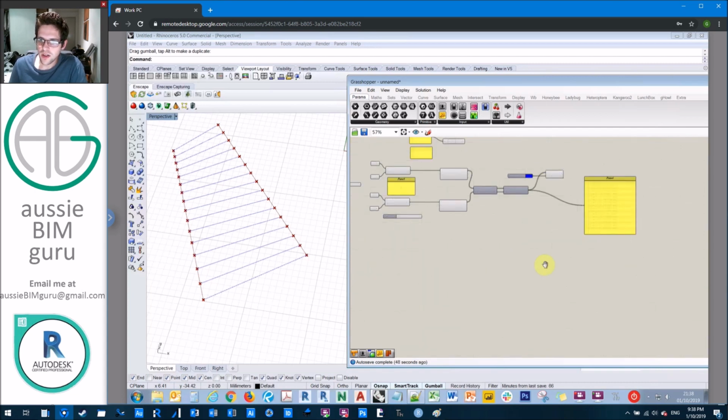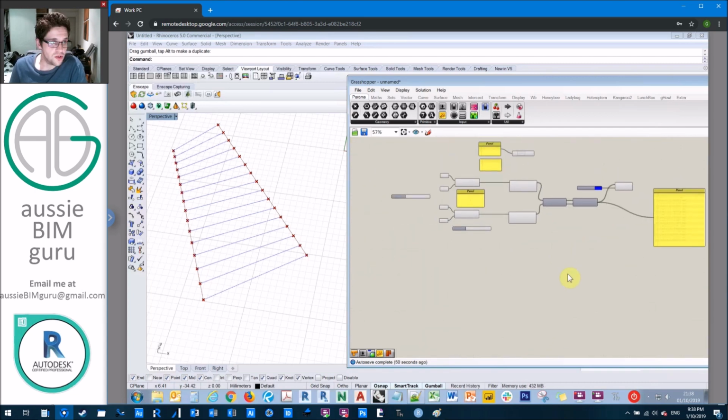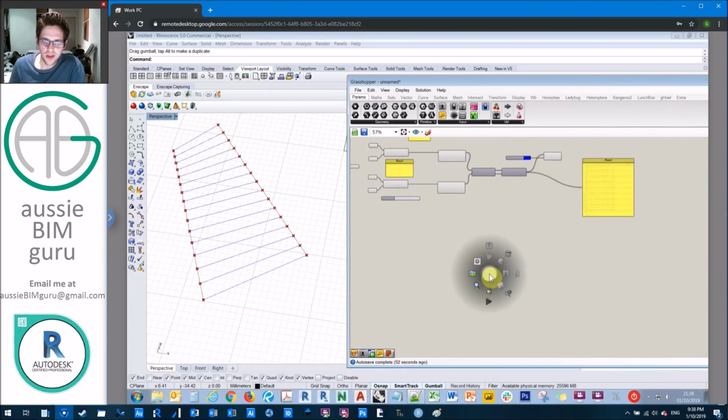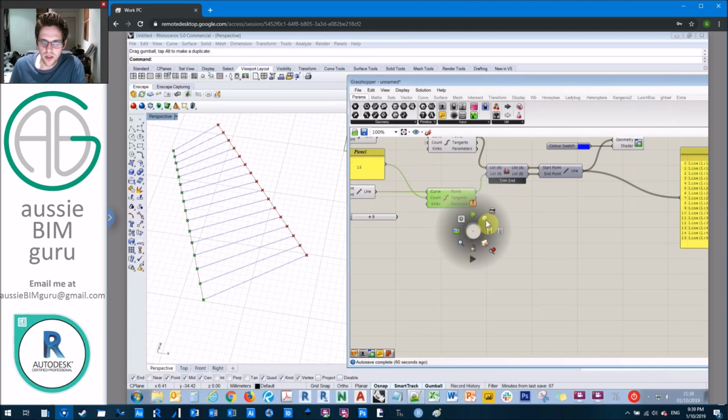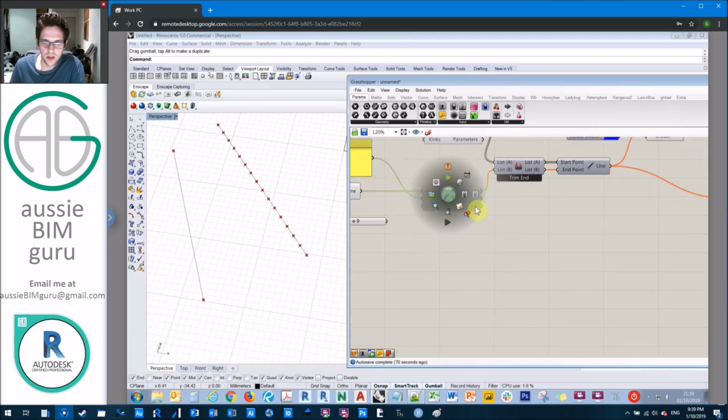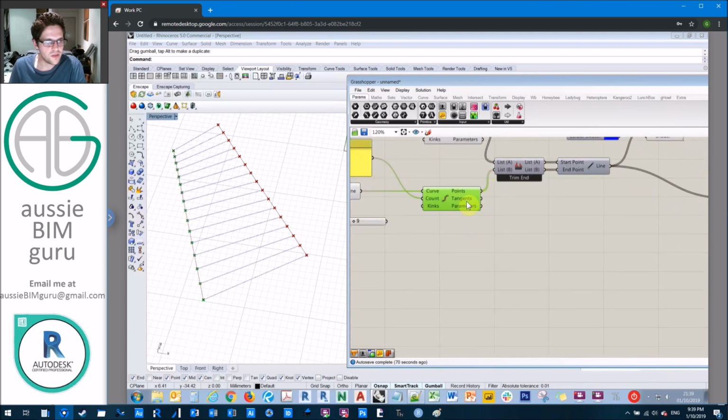Okay, so one thing I haven't touched on yet is what's called the radial menu. So if you middle click at any point, you'll get a whole bunch of commands available on the quick command essentially. So one really helpful one is you can obviously middle click and you can turn off preview really quickly. So I can disable preview. I can disable a node as well really quickly. So it saves you just having to click a few times and navigate through menus.